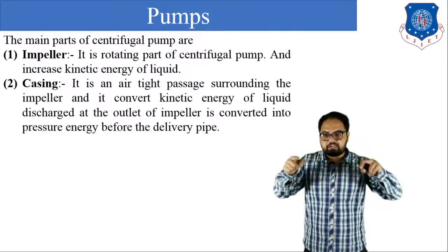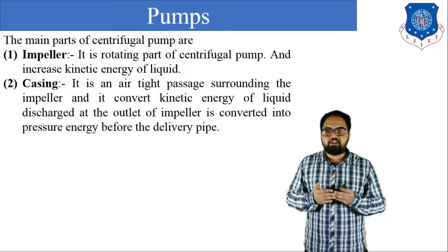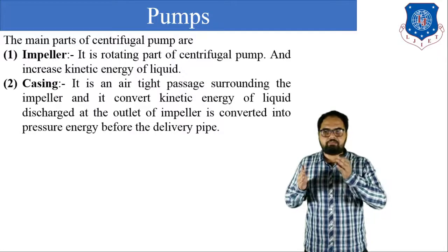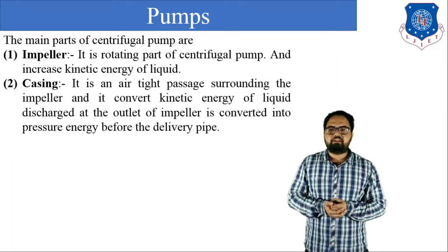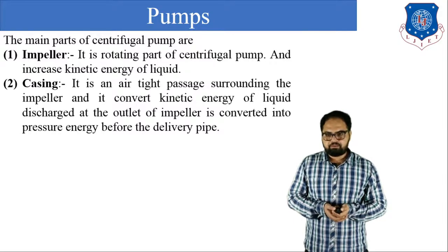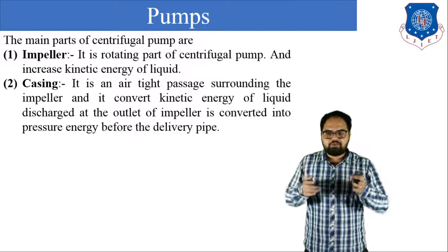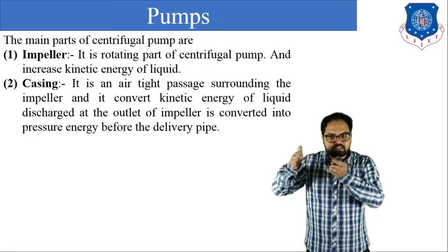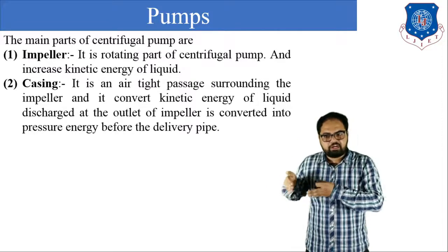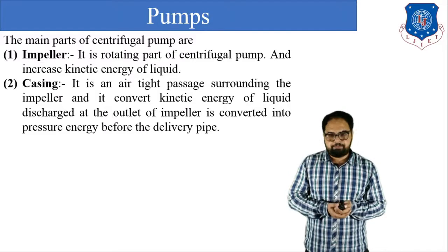Casing is an airtight passage which surrounds the impeller, and it converts the kinetic energy of the liquid which leaves the impeller into pressure energy of the liquid before it leaves through the delivery pipe.